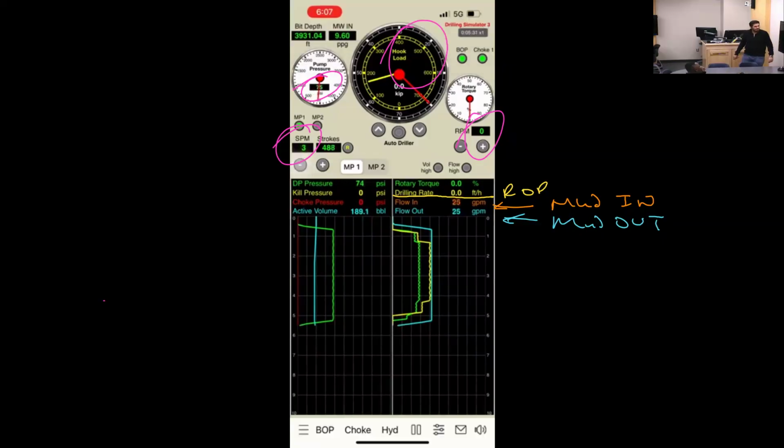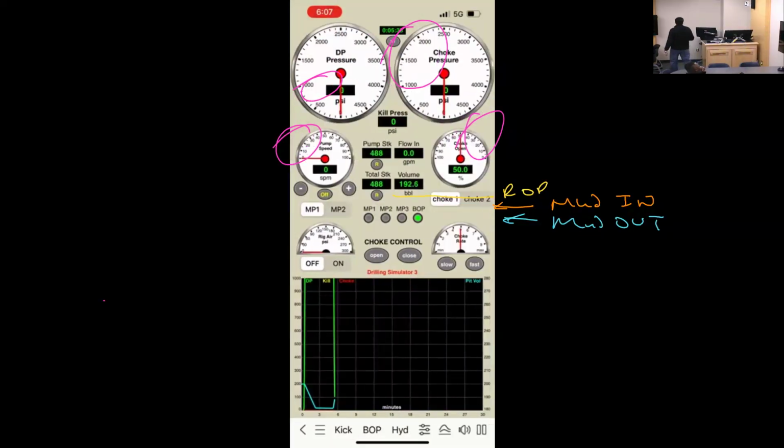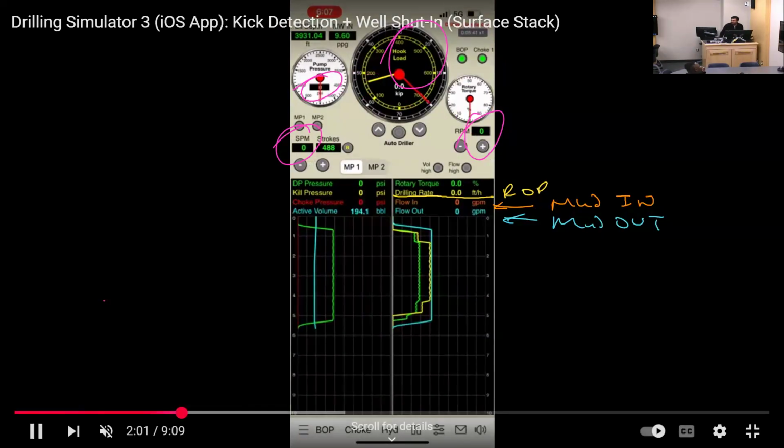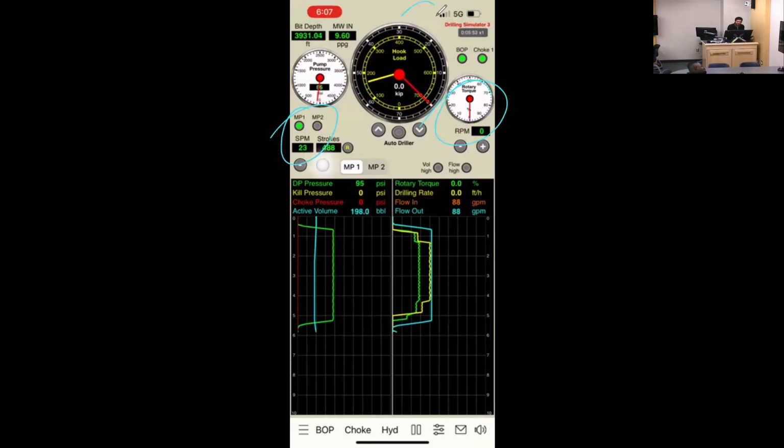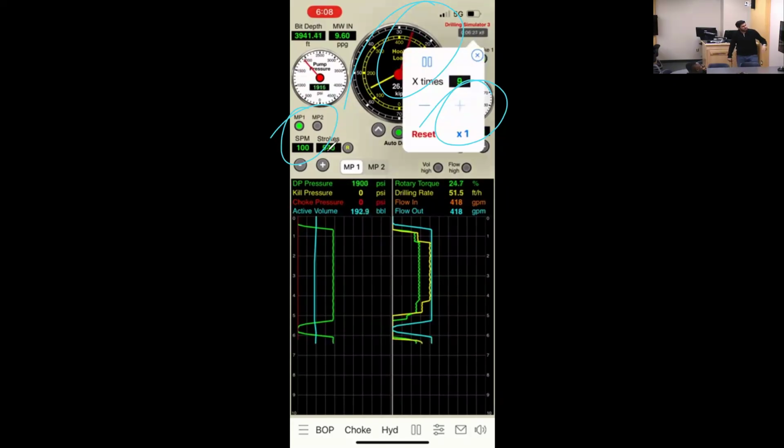Okay. Now it's going to go to 0. You see, all of them 0. That means I'm fine. Nothing is going wrong. So I'm going to go back into drilling. I will start again the other way around: first circulating, rotating, apply weight on the bit. And then when I stop drilling, I go the other way. I will keep on drilling. 100, 60, 27. So I go down to 27, 26. And I'm speeding it up.